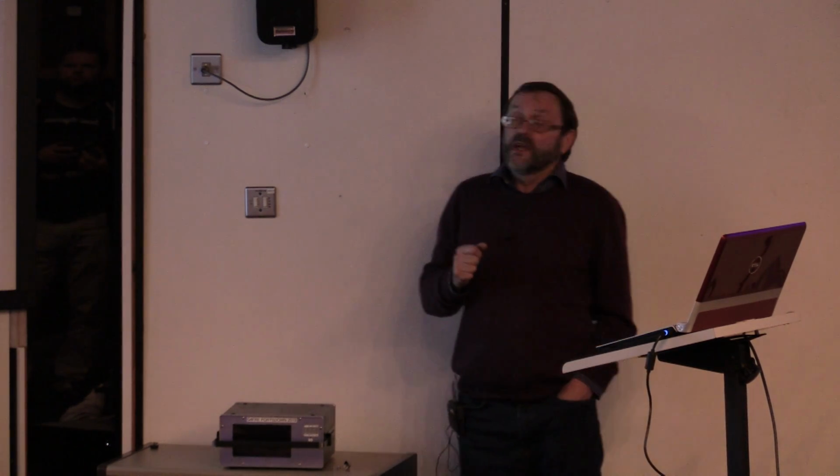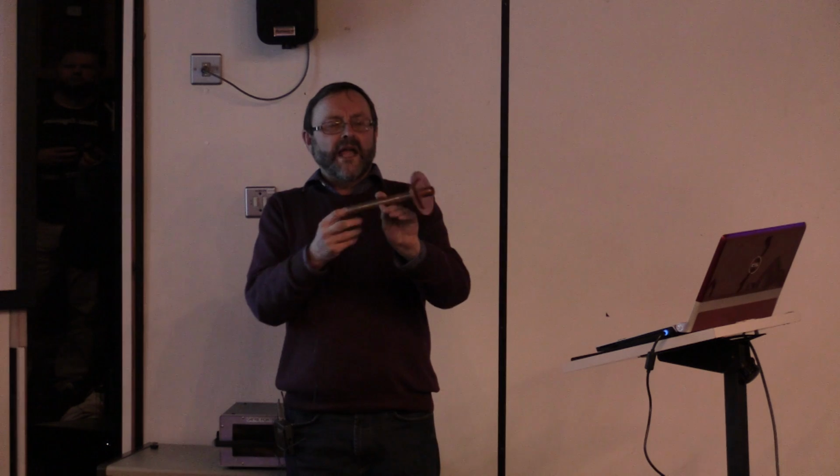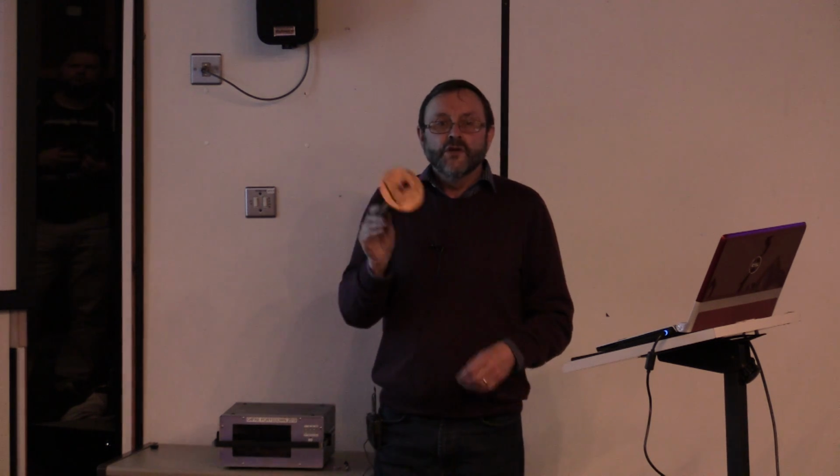For us, there's probably only one show in town, and that's the one that somebody's stolen from. No, it's back with you. So this feed, very good. If you didn't get it, the LNB goes on the back end and looks through the 22mm water pipe as a waveguide, and the patch on the front, which is the right-hand circular 2.4 gig patch, all at Mike's left-hand circular, because it's going into the dish to come out right-hand.